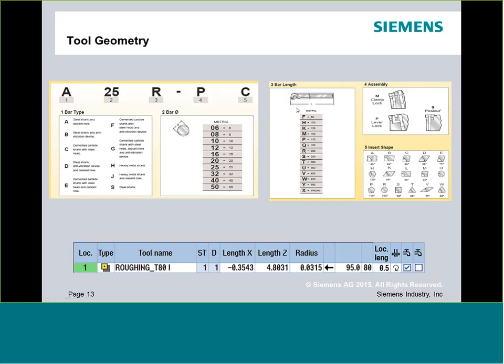And there's one critical variable that's not typically shown in the standard IC, but it's what's called your minimum bore diameter. So really what that is saying, if I look at this picture in the detail 3, what size hole can this fit without the back side of the tool physically hitting the back? That would be your minimum bore diameter. That is a very critical parameter to know. It is not compensated from the control standpoint, so you need to compensate for it when you start to write your parts and methodize your physical parts.